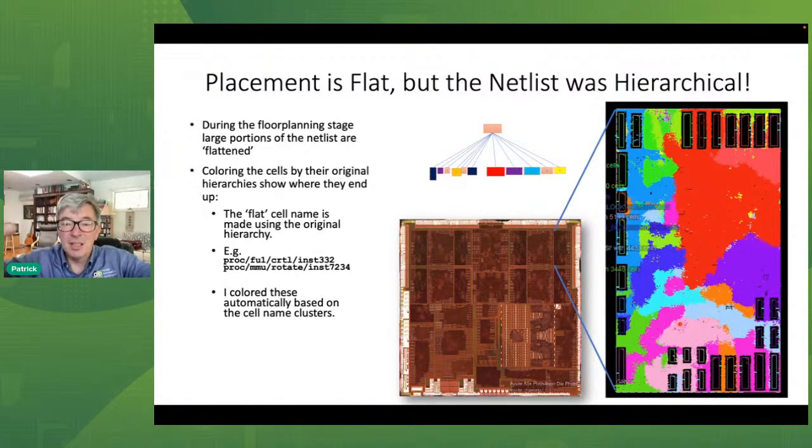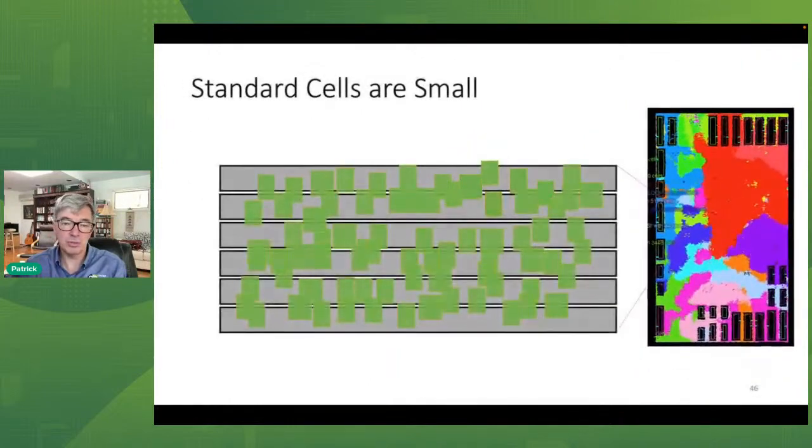And that's also what you really want, because you kind of want to break up that hierarchy, that rigid structure, to allow things to flow into each other, and that way have a much better solution. But there are limits, of course. Until now, what we can do flat is maybe up to 10 million standard cells in one shot. That's still very large. I mean, that can be many microprocessors. But if we want to make chips that contain billions of transistors, I'll have several of those blocks, of course.